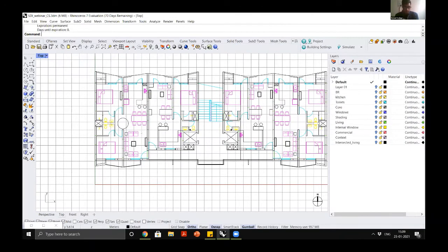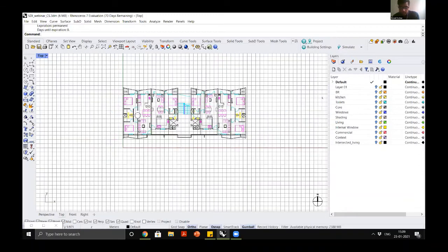As I was mentioning, we have to model each and every room as a thermal zone, because each and every room will have different exposures, first of all, to the outdoors, and also it will have different occupancy and internal loads. To begin with, we will start looking at how do you actually set up your model.